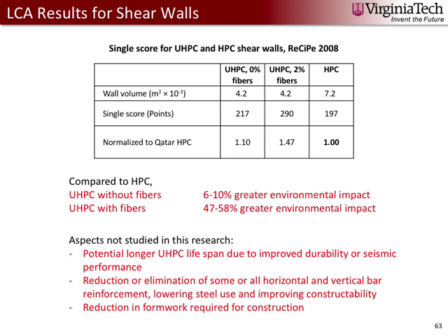I would like to put a note on these results, as there are several aspects that haven't been studied in this research that could change these results. One is the potential longer lifespan of the UHPC shear wall because it has higher durability and also better seismic performance. So the UHPC shear wall, if it was in a very corrosive environment, might last significantly longer than the HPC shear wall, and that would significantly affect these sustainability results here.